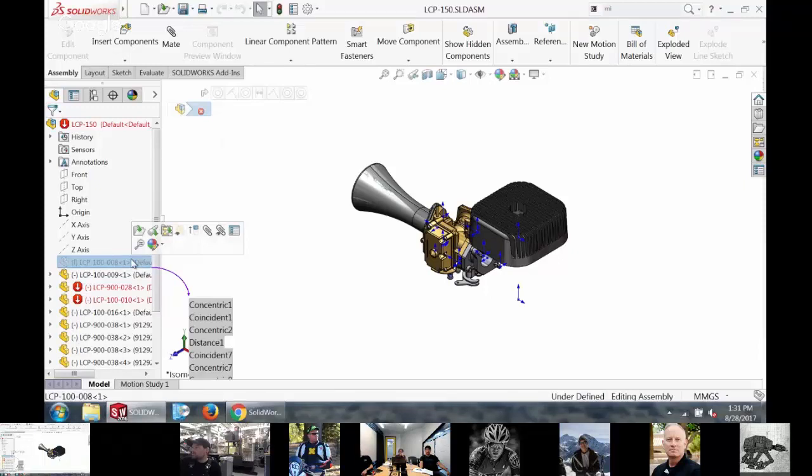every SolidWorks file gets marked with certain indicators. What machine was it drawn on? What date did it get started on? These types of things. Whenever SolidWorks opens an assembly, it checks all those first. And it says, hey, this part called cylinder 1 is not the one that was created in April. This is the one that you created in August.